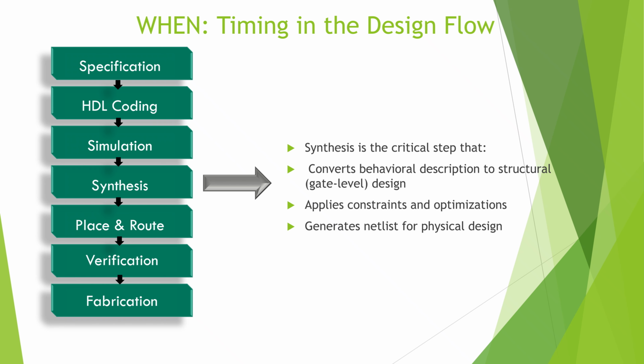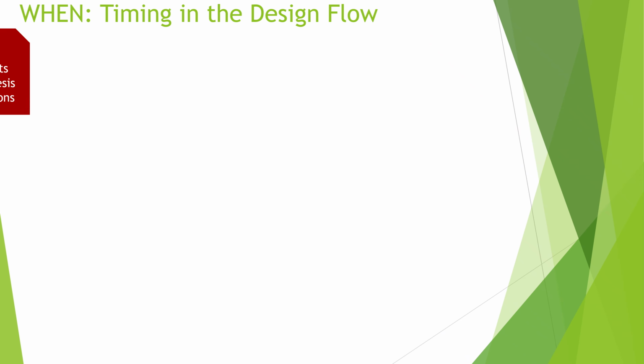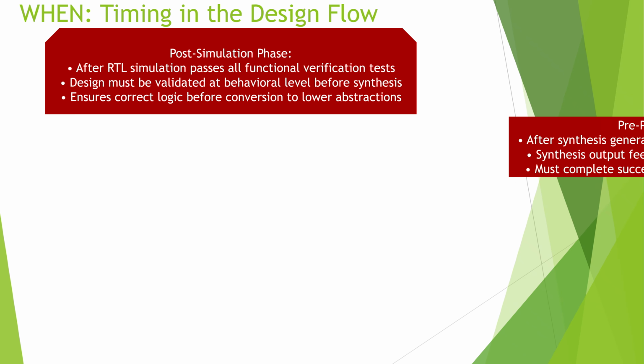Exactly. You should not push half-tested RTL into synthesis. First, fix logical bugs at RTL and simulation, then move into synthesis.